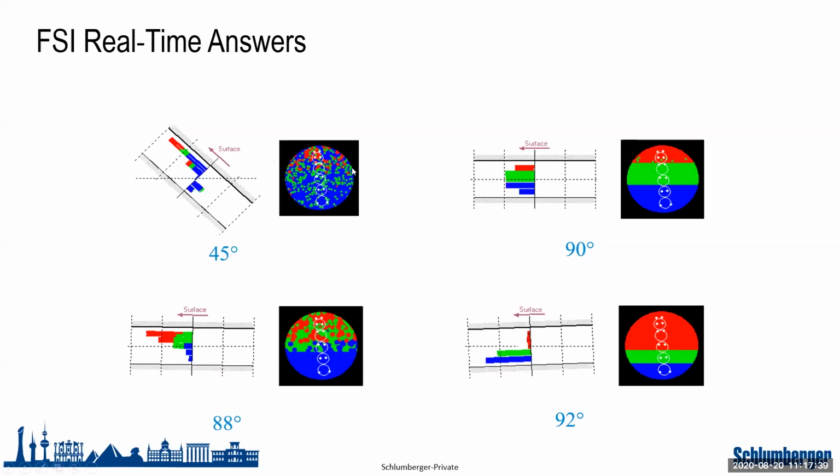And you can see, for example, at 45 degrees, these big circles are my main spinners, and the white dots are the position of my water holdup and gas holdup sensors at different levels. And I can see at 45 degrees I still have sort of a bubble flow, but I have my water suffering from recirculation, yeah? You can see the water moving down.